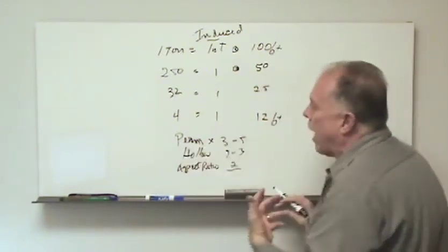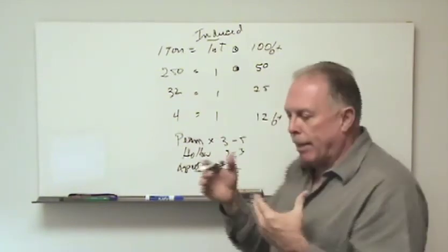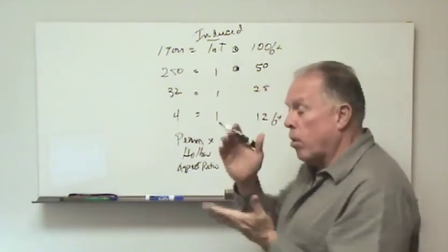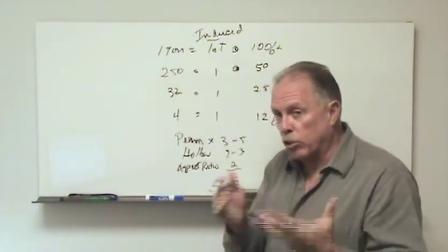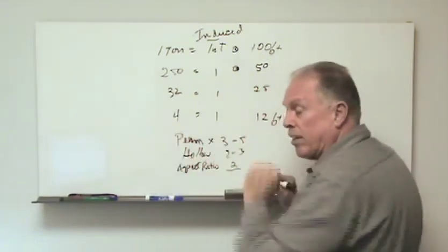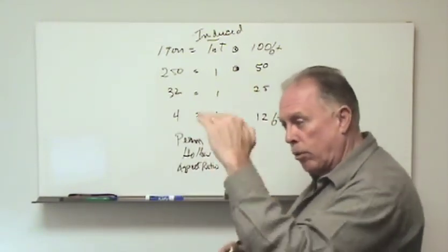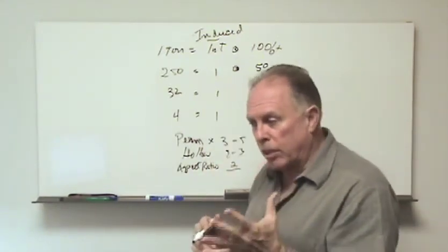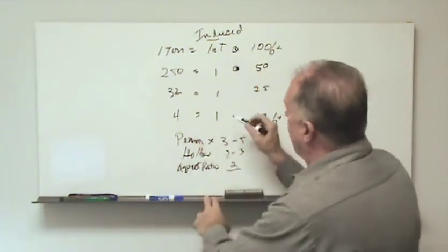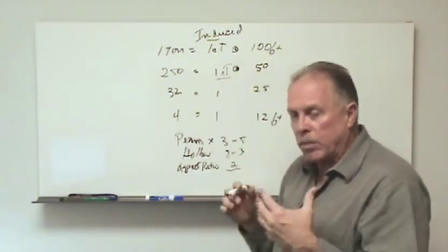So when we actually design the survey to find a given object, we can take a couple of different tacks on this. We can, for instance, go with the most conservative estimate. The conservative estimate would then say that we don't take these factors into consideration. And when we make our line spacing or consider how deep we should tow the magnetometer in the water, we would actually say that probably somewhere around 1 nanotesla would be our limits of detectability.